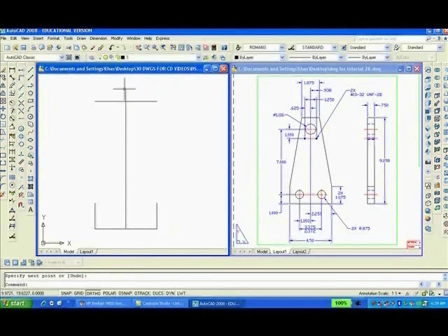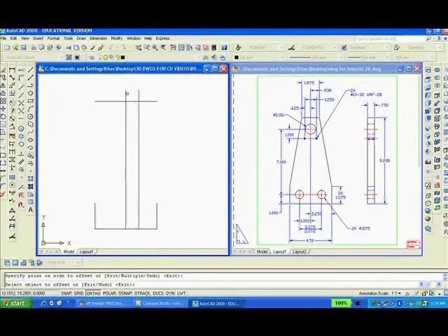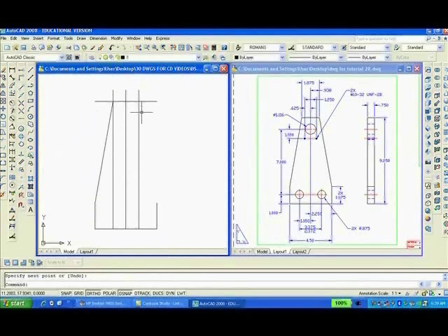and now we'll offset, enter, 0.938, enter. Offset there and there, so that we'll be able to draw a line and connect, well, O-snap has to be on. We want to connect that point with that one, enter. Enter again, repeat the command, connect that with that, enter.